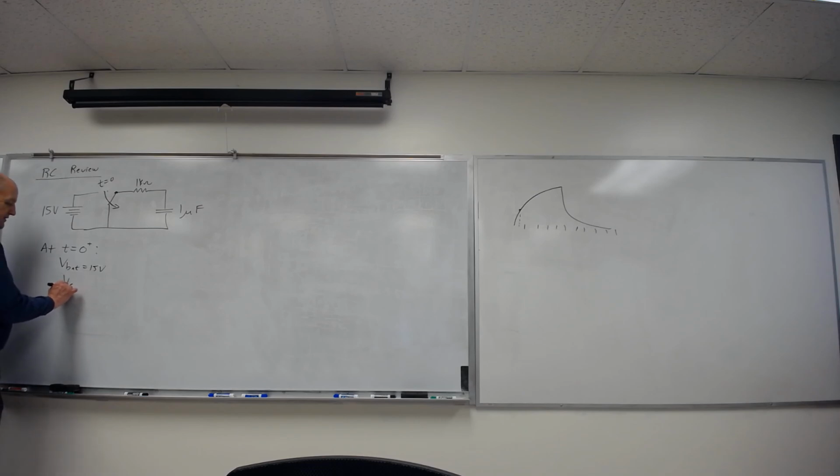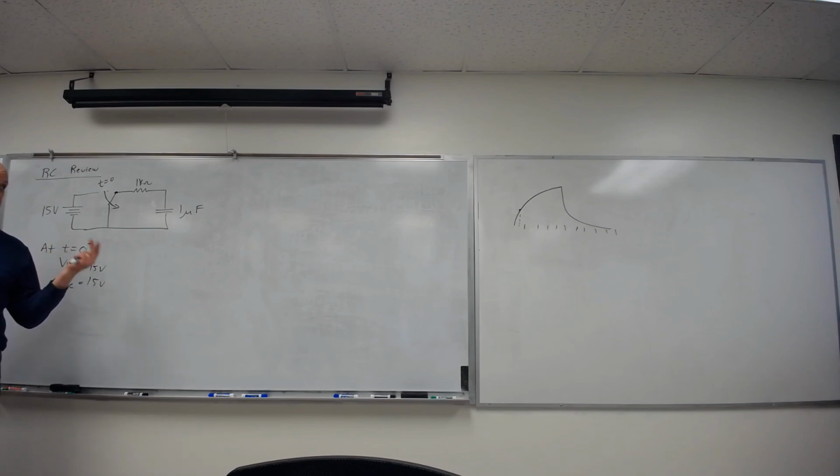The capacitor voltage cannot instantly change because it's got a bunch of charge sitting on this plate of the capacitor. In theory, if I totally disconnect the capacitor and take it away and don't touch the ends, let anything drain, I'll measure it, it's still 15 volts. So it just sits there and holds it forever. Real capacitors will sit there and hold it for a while. When you're doing this experiment, you frequently have to touch something across the 2 ends to make it drain off so you can move on.